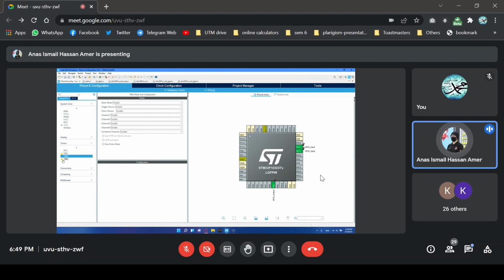You can notice that some timers have this yellow warning triangle. This is because we're using the pins for this timer, PWM for example, for another purpose, which is, for example, the inputs or the outputs. So that's why they're showing a little warning. So we don't care. We just use timer 2. So we're presented with a lot of options, out of which we need to choose the clock source. We're using the internal clock or the internal oscillator, so we'll choose the internal clock.